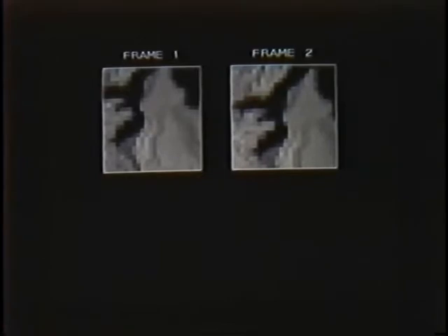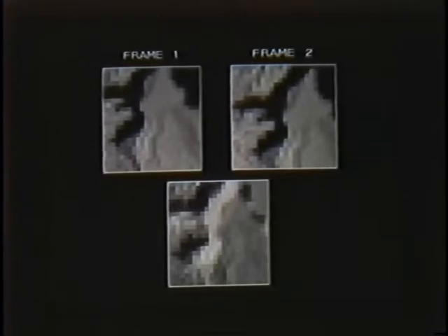Before we begin our jitter estimation process, let's compare the 2 frames just as they are. We'll do this in 2 ways. First, let's difference the 2 frames and note the clutter leakage. Recall that the more 2 frames are similar, the less clutter leakage we should expect in their difference. In order to quantitatively evaluate the clutter leakage, we will relate it to the standard deviation of the image intensity in the difference frame.